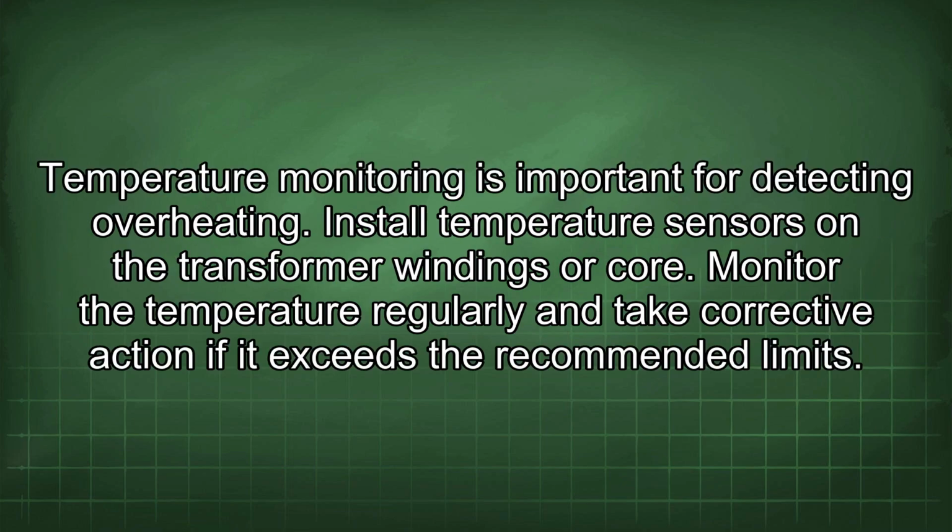Temperature monitoring is important for detecting overheating. Install temperature sensors in the transformer windings or core. Monitor the temperature regularly and take corrective action if it exceeds the recommended limits.